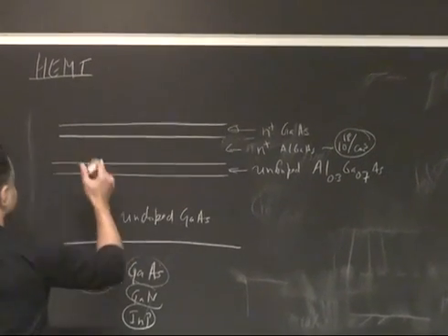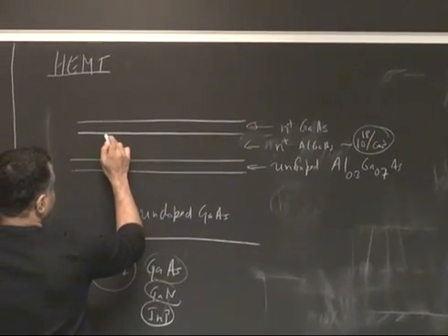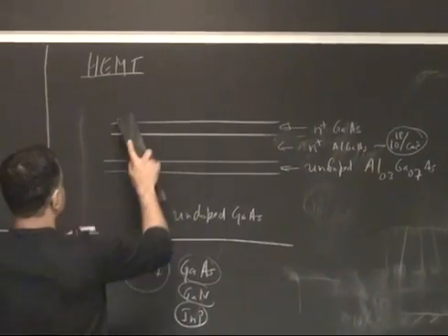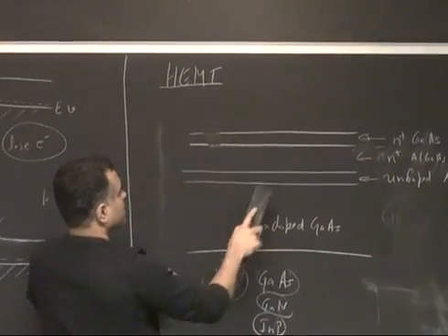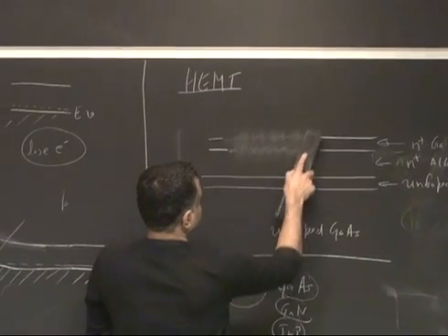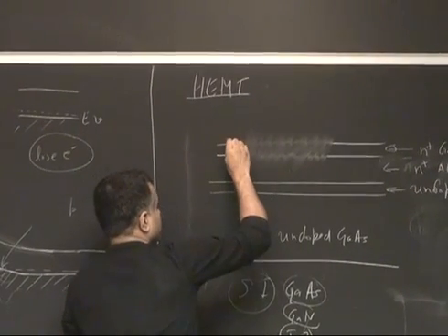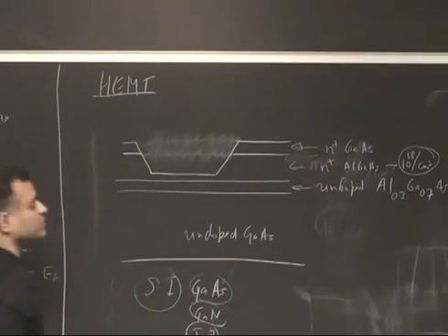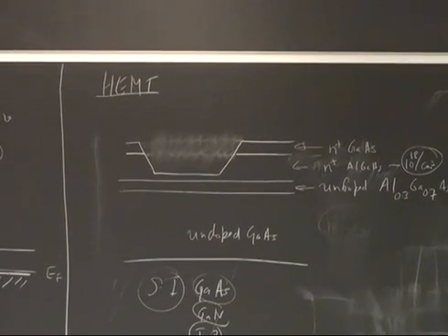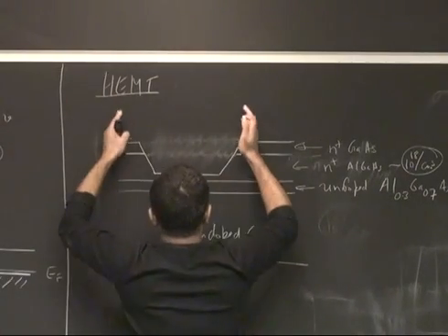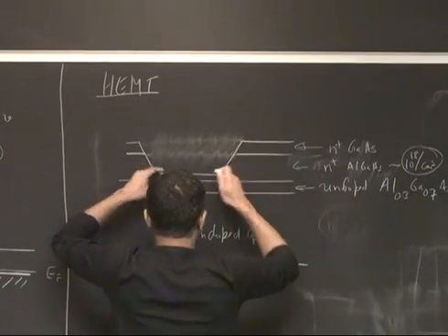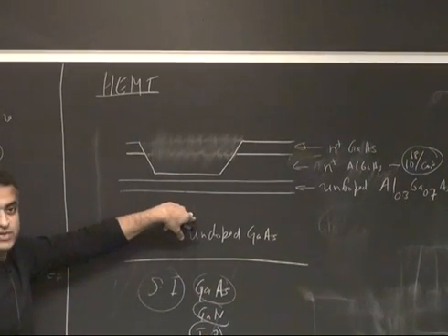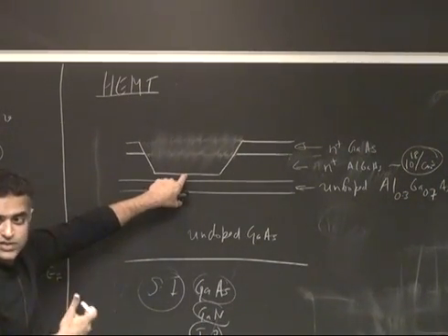After the growth, you take it to the clean room and do some lithography on it. The way you're going to make the device is you're going to etch it down. You remove this part of the region, and it removes those regions. After the growth, you put on a mask, do an optical illumination, remove the mask, then etch it. But etch and then stop here. Don't go all the way. It's very important where you stop, because that's going to control the threshold voltage of the transistor and all that stuff.